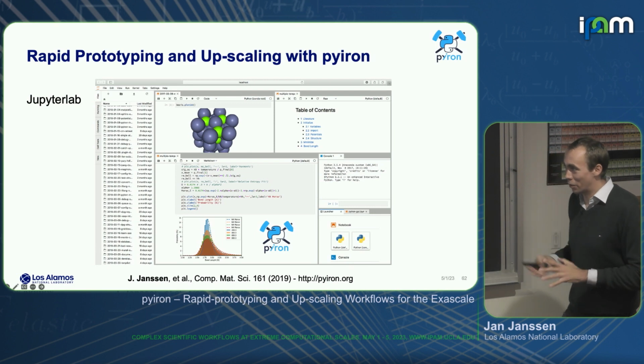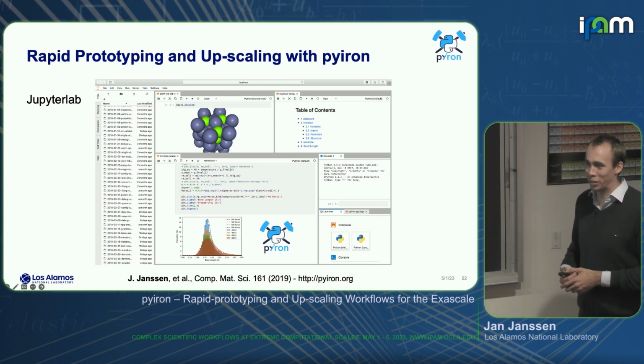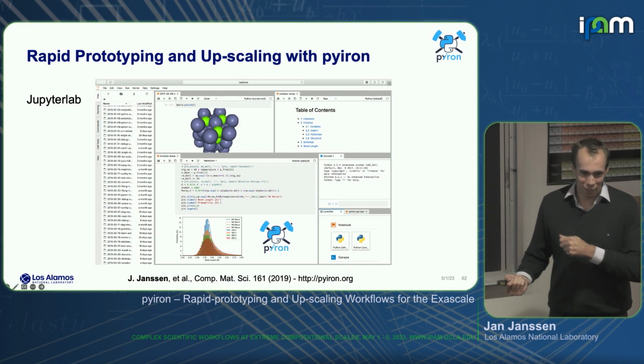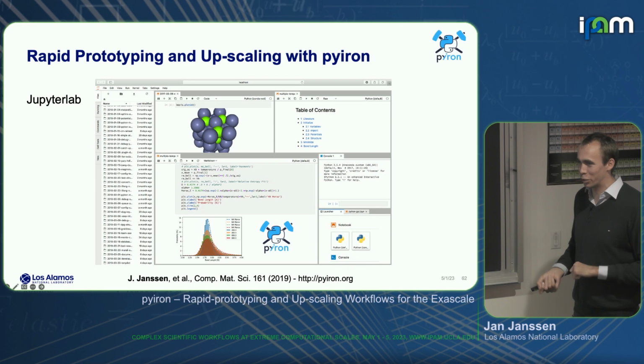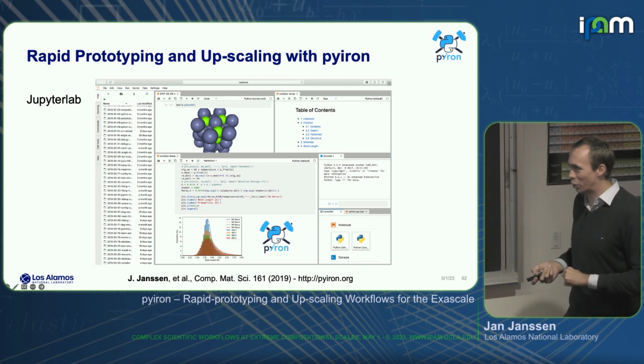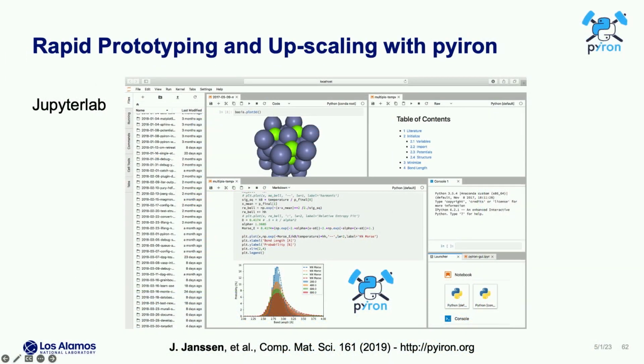And we don't have statistics like how much time this saved, but we know from previous experience that many people submitted calculations with some overlapping atoms, or with angstrom not converted correctly, and these calculations just run forever and give very cryptic error messages, and then you increase the CPU resource and so on, right? So it's very helpful to just look at the structure before you submit your calculation to get a first feeling there.